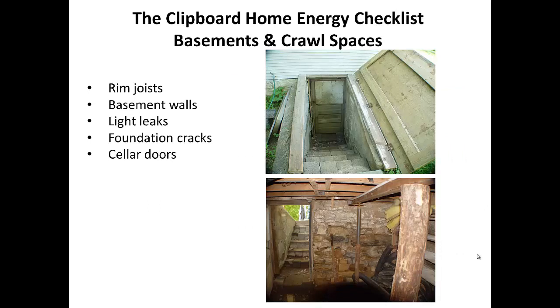Cellar doors are an area that typically go into a crawl space, or a larger crawl space is what this kind of is. It's kind of a glorified cellar basement. But this door here, I guarantee you, is very poorly constructed to protect against getting the area below the house down here cold. You can see there's a gap underneath the door here. So cellar doors to either crawl spaces or cellars are another area on the checklist.